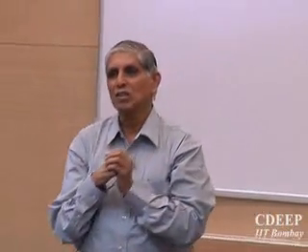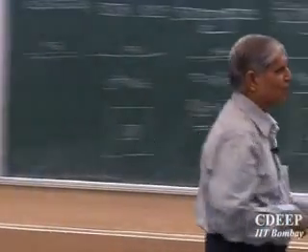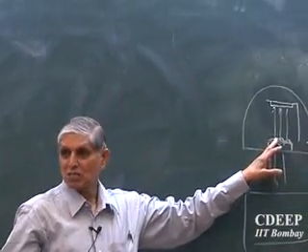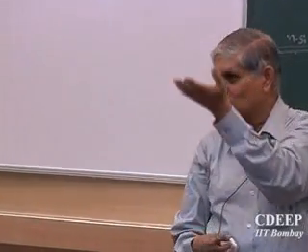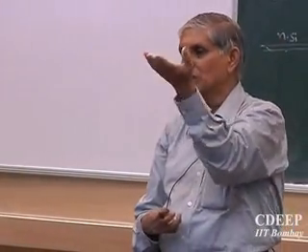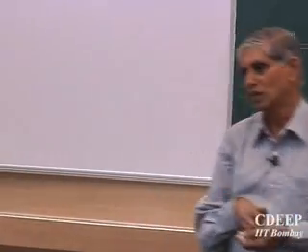So what is the advantage of vacuum otherwise? In air, there is a quantity called the mean free path, which is very small. It is proportional to 1 upon P. So the smaller the P you keep, the larger is the mean free path. What is the advantage of a larger mean free path? The aluminium atoms will go vertically upwards before they collide with each other. In air, that was also a problem, they scatter. Here, they go vertically up. So you know, by time or by measurement, how much thickness of aluminium you are depositing.